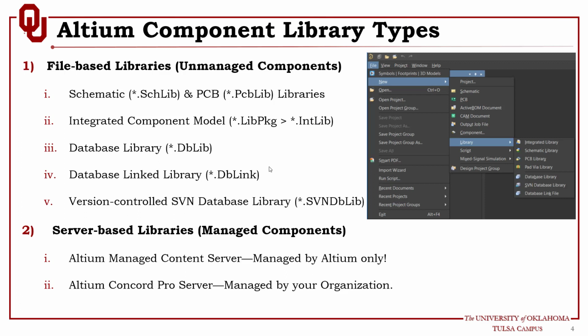The advantage of combining into an integrated library is that all component information is available in a single portable and secure file. So in this case, you don't have to worry about anything. Once you create your integrated library, you can add components to it in the future, anytime, and compile it. Once you compile it, it's a single container that is secured and portable. You can move it from one PC to another. You can put it on a network drive and link to it so you can use it from anywhere.